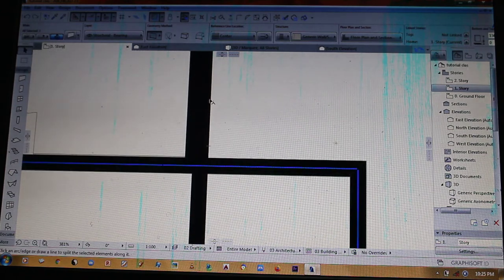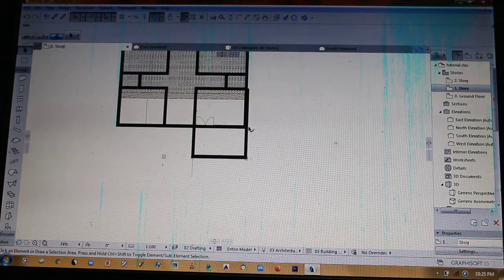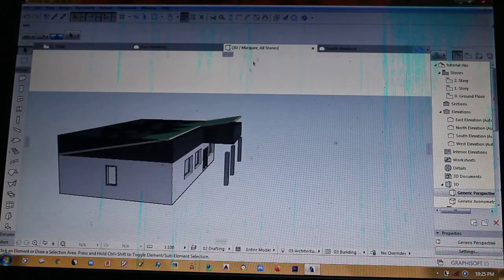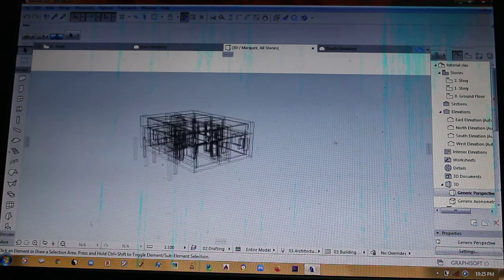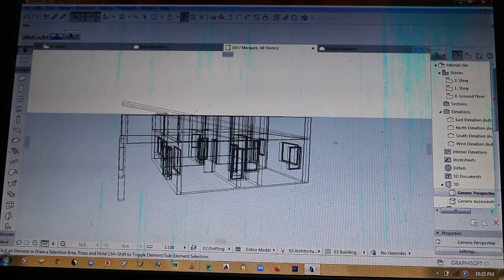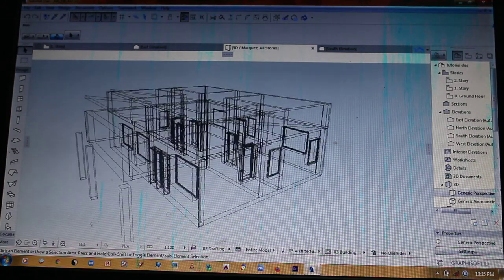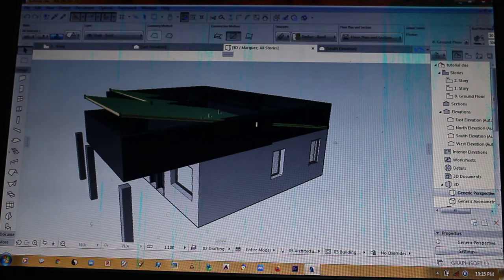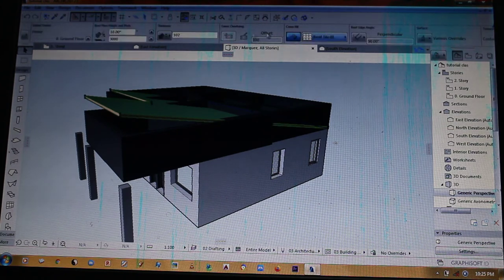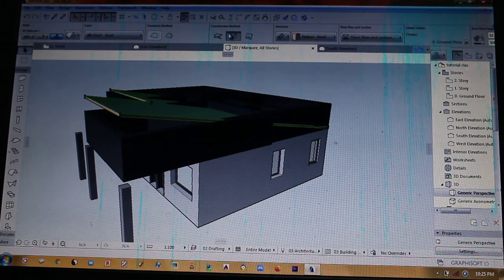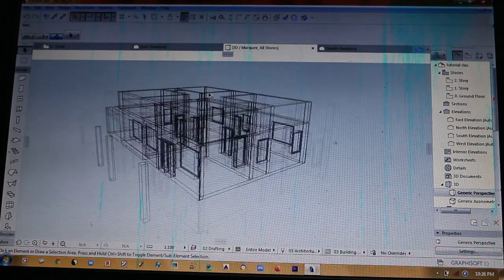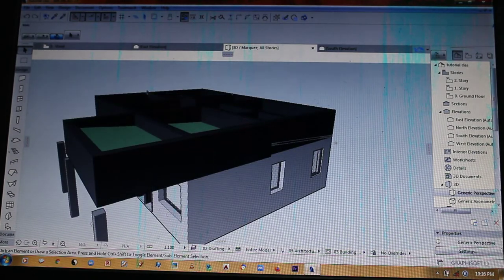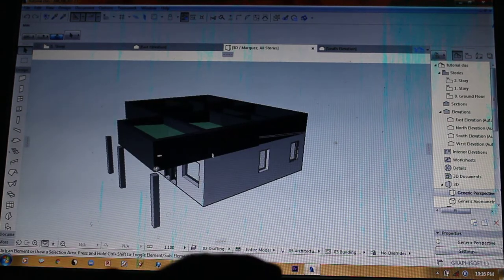So guys, let's look at what we created. Okay, so now once you go there, you will see that we have something more like this. Okay, and then our roof is still at a higher slope. Okay, let's reduce it. Let's give it maybe, let's say 5. Okay, good. And then these walls, in construction we don't have these interior walls once we are using this kind of parapet hidden roof. Okay, what we are going to do,